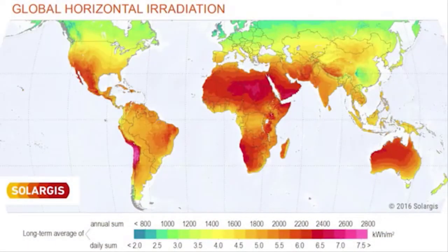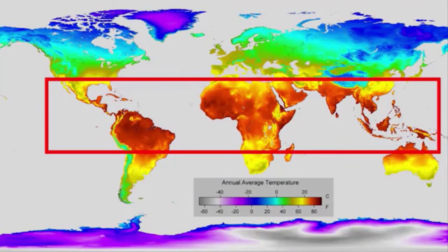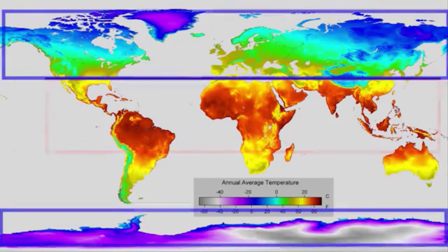Now that we know how to calculate annual energy demand, we're going to move forward and look at sizing the whole photovoltaic system. Solar energy insolation, or incident solar radiation, varies across the globe and varies due to differences in latitude as well as climate. Oftentimes these are connected though. Places that are hot and sunny tend to be in lower latitudes closer to the equator, and places that are cooler and less sunny tend to be further from the equator at higher latitudes. However, there can still be a lot of variation because of local geography.